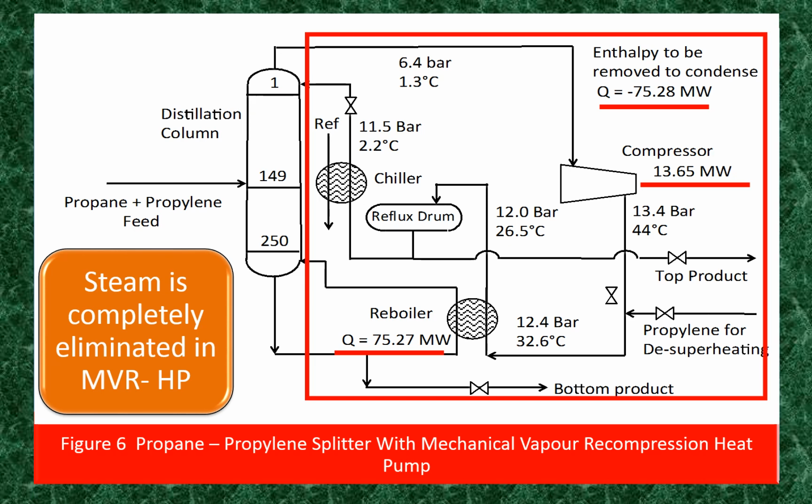In this analysis, I did not include the refrigerant load for the condenser in the conventional cryogenic distillation system because the load is part of the common refrigeration network of the entire plant. You need to have full data to include this in the analysis.